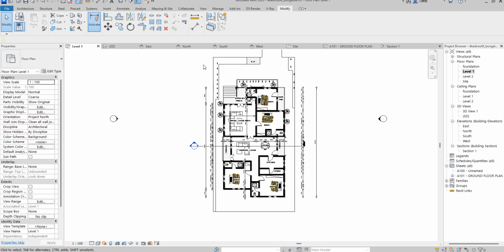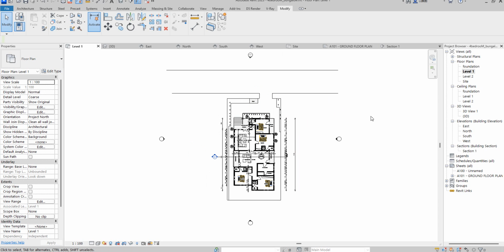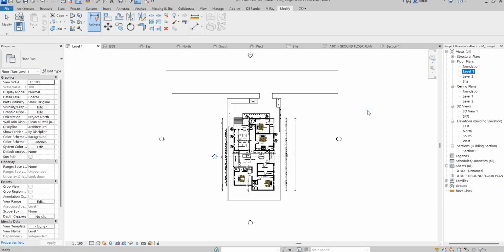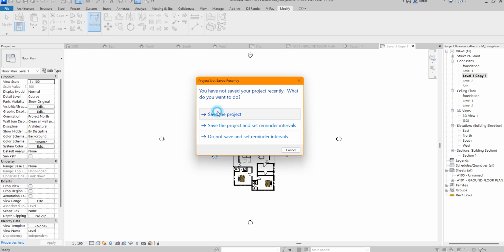There are two ways to do it. You can duplicate entire thing, then later that one that you did, let me quickly demonstrate that for you so that I will not be speaking too much English. So what I will do here is that this level 2 now, I'll just say copy. What will you do? You just say duplicate view. If you duplicate a view, only the model will go, all the annotations will disappear. Let's do that and test. So you just say duplicate.